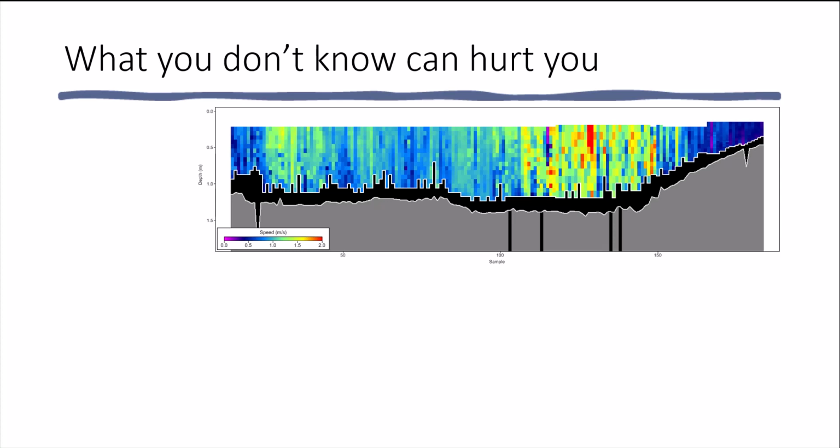What you don't know can hurt you. This is the primary reason for discussing how ADCPs measure the Doppler shift, the various modes of operation, and how the software processes the data. Previously, I told you that for SonTek, if bottom track is invalid, the last valid value is held for 9 samples and then set to 0.